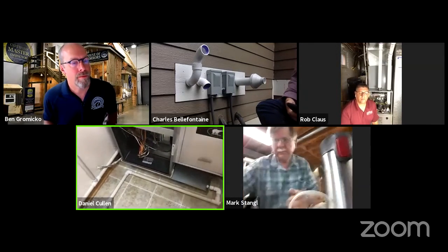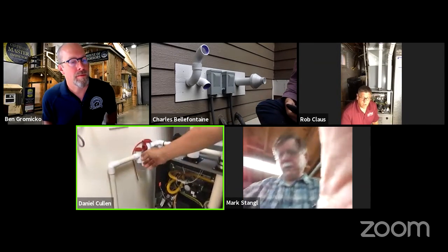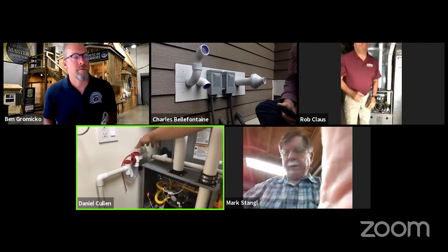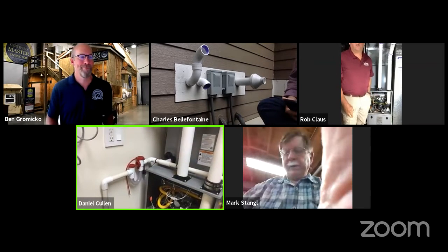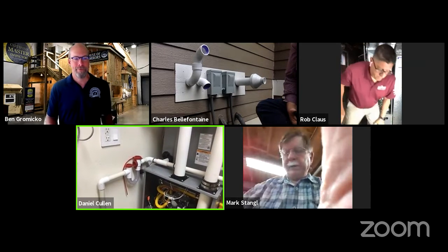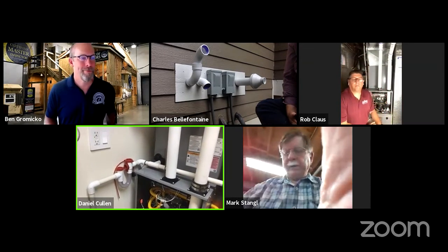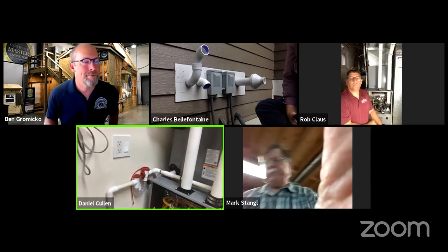And this is a little pet peeve of mine. I hate feeling all the cold air and hot air blowing out of untrapped condensate drain pipe. So I had him put in the nice pre-made trap.